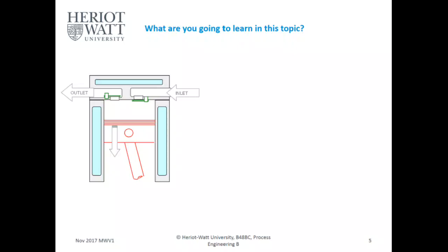Let's talk about the reciprocating compressors, how they operate. So imagine the piston moves. So the piston moves down. This is not the best drawing, but this piston moves down. As it moves down, it creates a vacuum or a pressure differential. So as soon as it moves down, your inlet valve opens up. Just imagine your inlet valve opening up, so it lets the gas in.